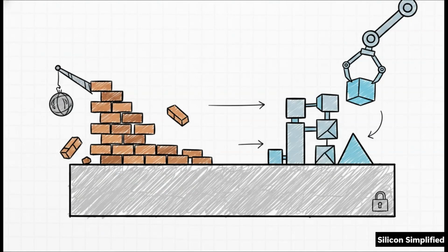It completely eliminates the need for virtual sequencers just to pass configuration data. It also gives you powerful new tools like retrieving data by its type rather than just its name. And when you pair this with those UVM factory overrides we mentioned earlier, you achieve ultimate flexibility. In a real project, you could use a type override to globally replace all standard packets with error packets for a specific test. Or you could use an instance override to precisely target one specific driver deep in the hierarchy, swapping it with an extended driver, all without touching your base code.